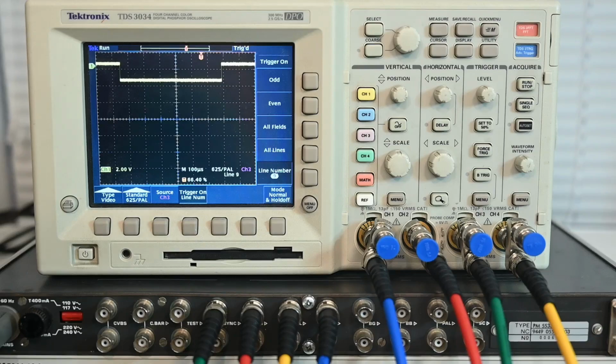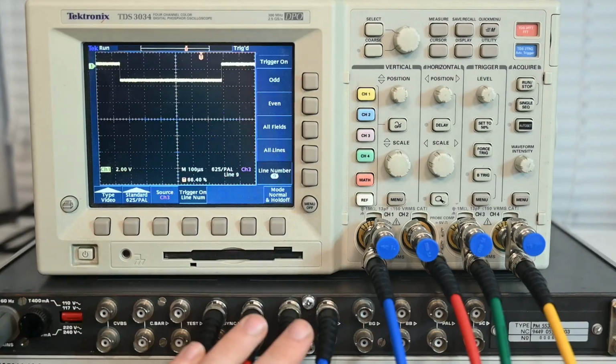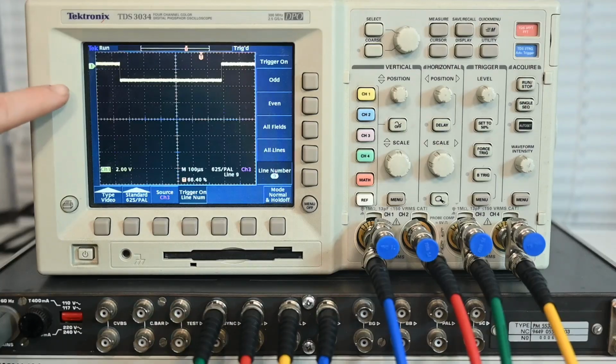Now the reason that we have this out is, as with the 4210, we have the full suite of ye olde sync signals available on the rear, which is certainly handy if you want to demonstrate them. Now as with before, we're going to start off with the 4 monochrome sync signals and we'll build up from there. What we're presently looking at is the vertical drive, and as we would expect, it's just a pulse which occurs at the beginning of every field.